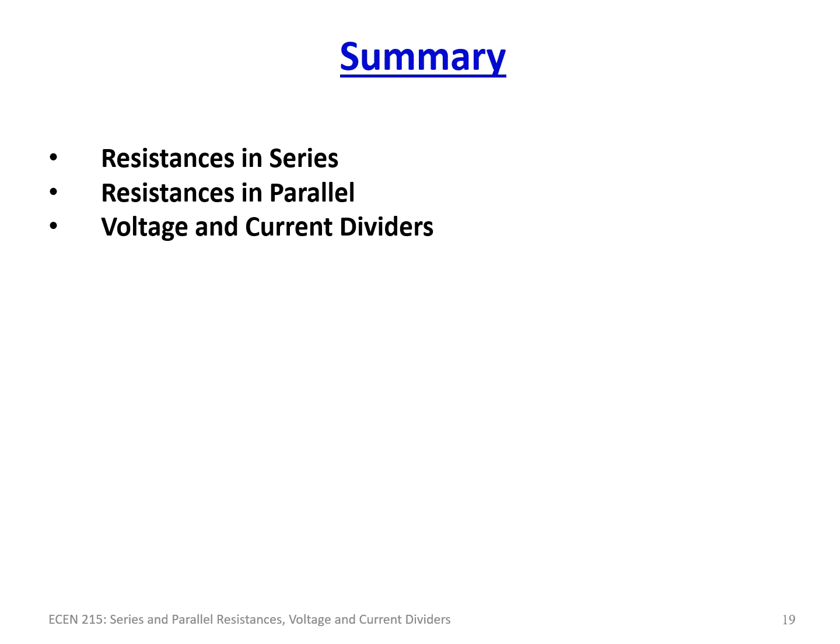So if Vin is 10 volts, the output voltage is equal to Vin times R2, the resistor in question that is being analyzed, over the sum of the resistances of a 2 element resistor divider or voltage divider circuit. You would have R2 over R1 plus R2 for the voltage across R2. If it's the voltage across R1, it would be R1 over R1 plus R2.